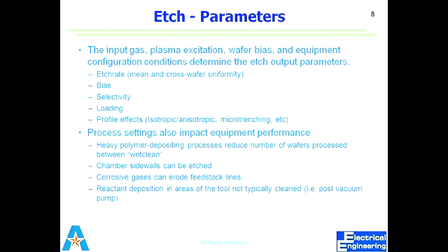So what is the potential that you are supplying between the two? What is the selectivity? What is the loading effect? We have not discussed the loading effect up till now, but I'll discuss it in the next slides. Profile effects, that is, what is the anisotropic ratio, or whether there is any micro trenching; we will discuss micro trenching as well in the next slides. So these are a few things that you already know, except the loading effect. I'll let you know what the loading effect is, but it is also important in etching.